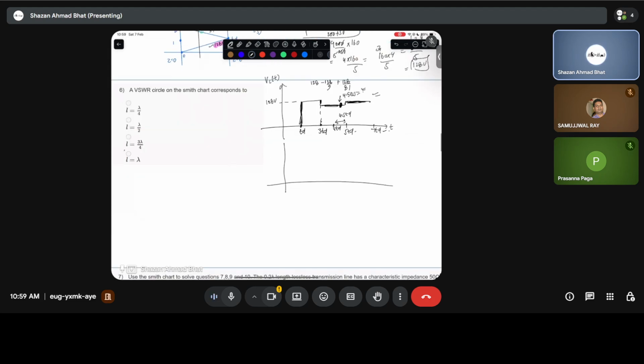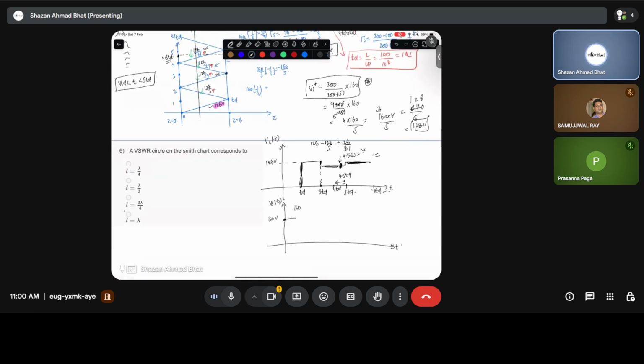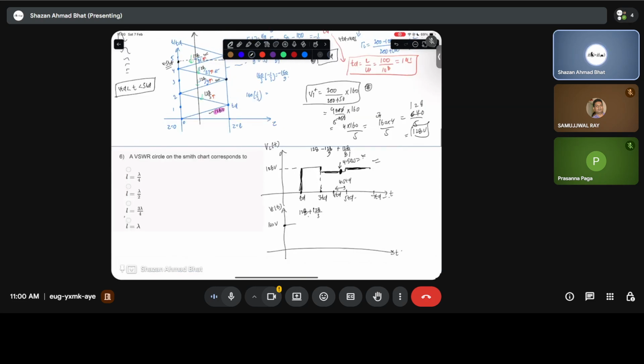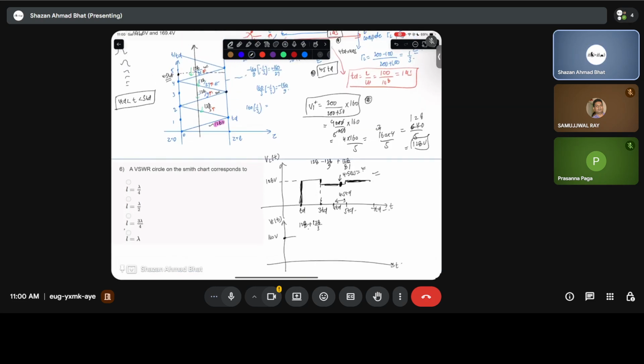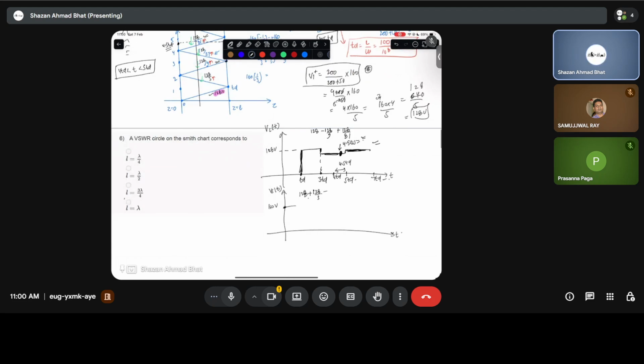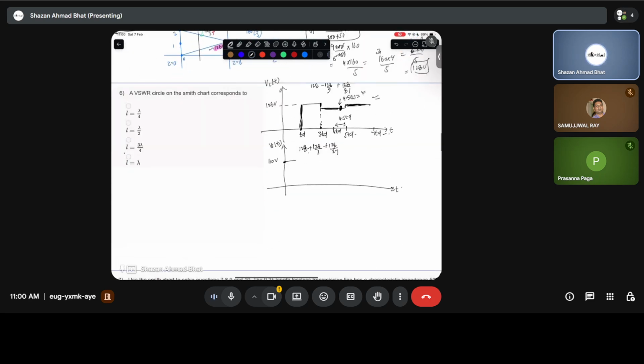And from the source end, if we draw the source end value, obviously the source end voltage is going to start initially at 160 volts, and then it will be plus 128, sorry, why am I writing 160? 128 plus 128 divided by 3, and then it will be 128 divided by 27, and that's it, up to 5TD.